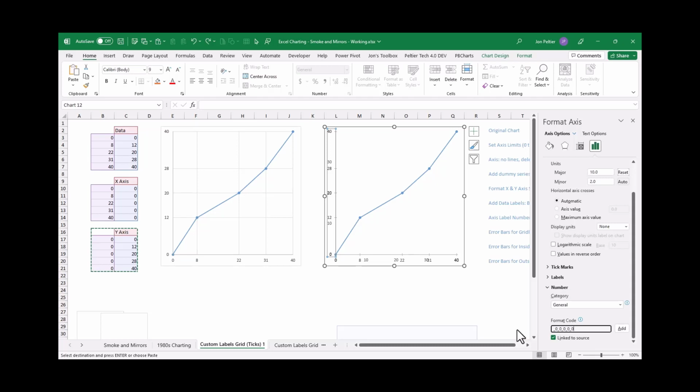Through some trial and error, I learned that 5 underscore zeros is just right for this, because I think charts aren't as smart as cells when it comes to these number formats, and the spacing isn't really quite one character width of 0. So you have to kind of overcompensate. And if I just leave it like that, if I get a 0 value, it'll leave a dash there, and I don't want a dash cluttering up the white space around my chart.